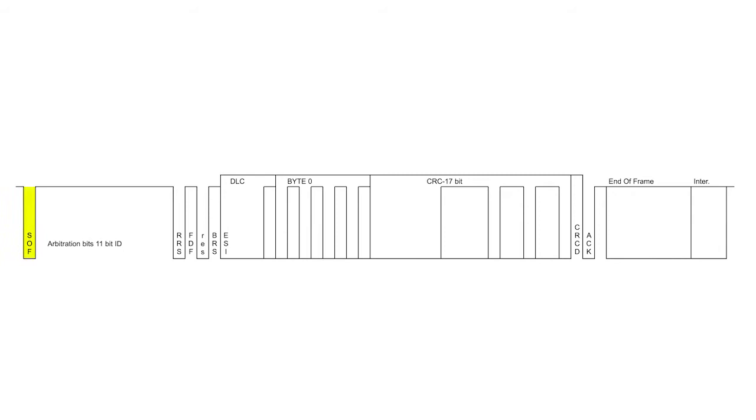The first bit in the CAN frame is the start of frame. This is a single bit that synchronizes all units connected to the CAN bus and starts the priority process. After this bit comes the priority section, where several units could be sending in parallel during the arbitration process. The CAN frame with the highest priority wins access to the bus line.